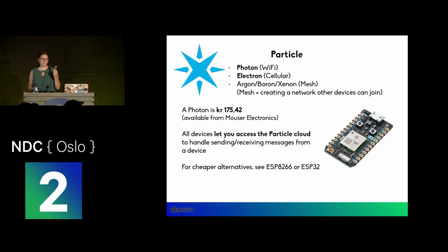But when you plug an Arduino in, it will just run the program you flash to it. With a Particle, when you plug power into it, it looks for a wireless connection. You set up the wireless connection at the beginning, and after that it will always connect to the wireless connections that it's seen before. But you program it over the air, through the internet or through VS Code. They have an extension for it. So this connects up to the internet and then to the Particle cloud.